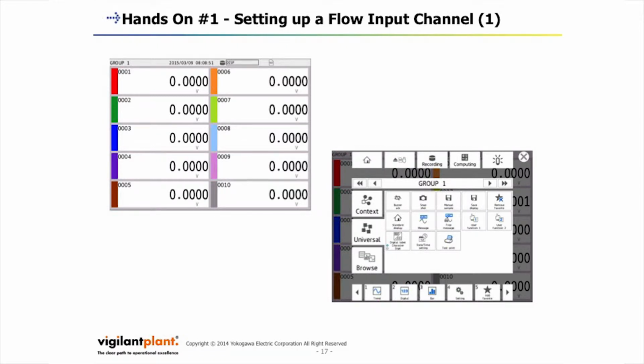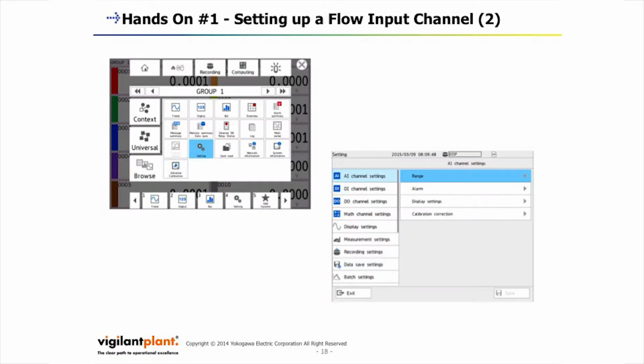First here, you'll need to press the menu key and bring up the screen for programming here. We need to make sure that recording and computing are not running, or any of the program changes that you try to make will not be saved, and you'll have to basically start all over again. So it's always wise to look here and make sure you see your recording and computing icon. If those are running, we'll have to stop those.